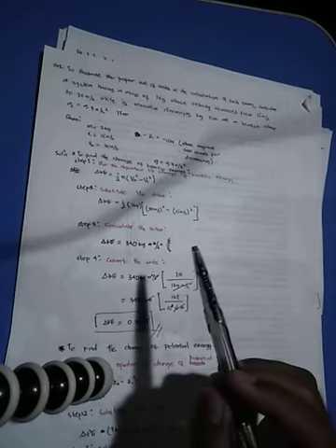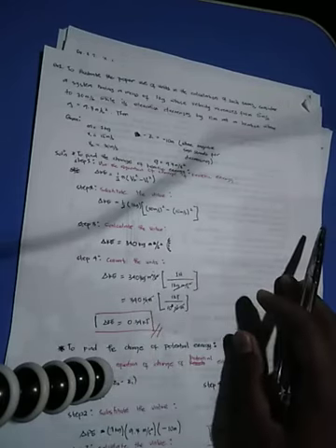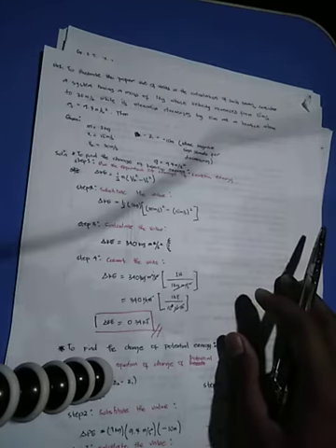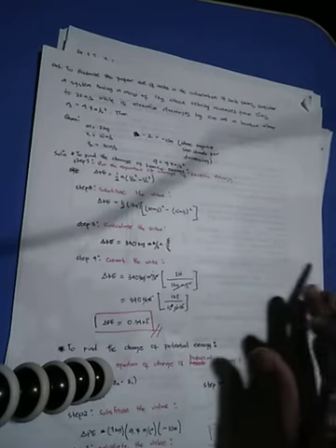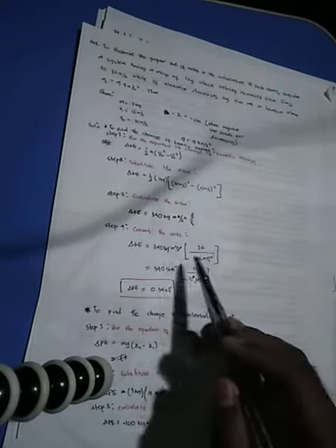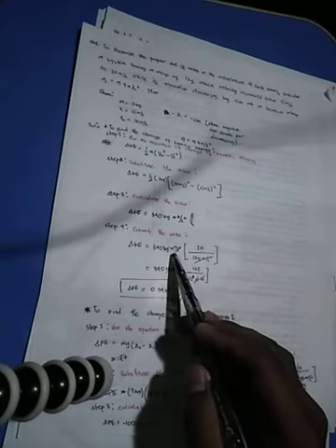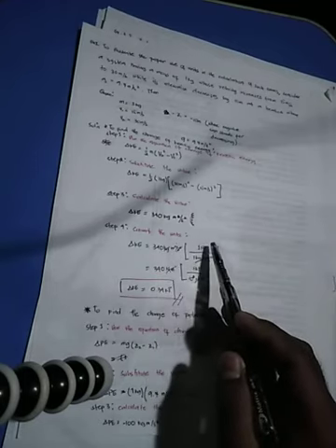So, step number 4, we have to convert these units, because the convenient unit in our manuals should be kilojoule, the most standard unit for energy. So we have to convert this kilogram meter squared per second squared into kilojoule. In step number 4, we have 1 Newton, which is equal to 1 kilogram meter per second squared.